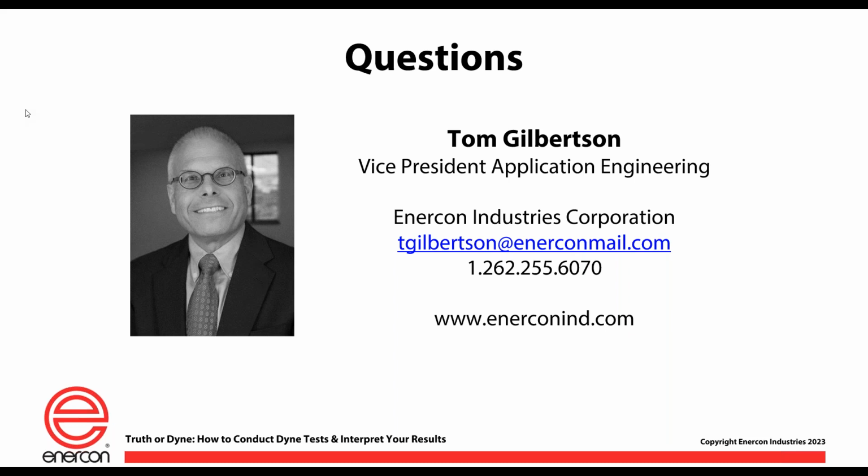Well, that's a great question. Let's face it, you could take that wide film and you could use a contact angle device. And remember the video we had where we graded out the sections where you identified like 32 dynes, 36, that kind of thing with a marker. You could probably do that on a wide film. That'd be a lot of effort. And because you're only measuring maybe a square inch at a time, if that, with a contact angle device, it'd be tough. I'm not sure, as they used to say, the juice is worth the squeeze there. But you could do it.